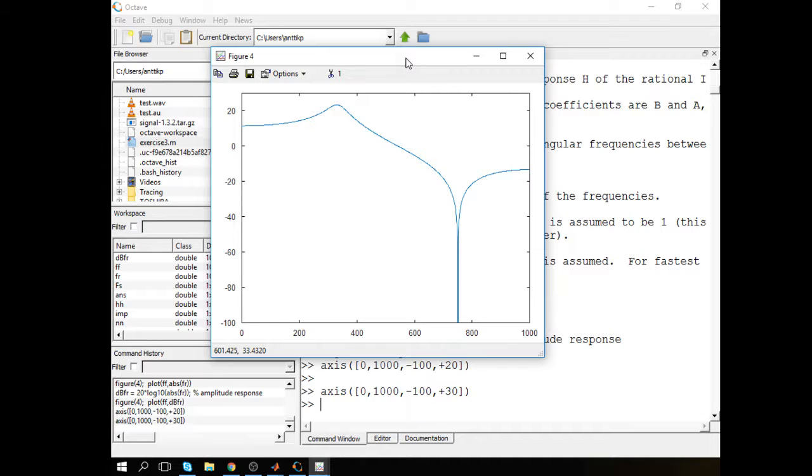The group delay. Actually, you can use FDA tool if you wish for the exercises. On MATLAB, there's a nice tool called FDA tool where you can actually do about the same things as in here.